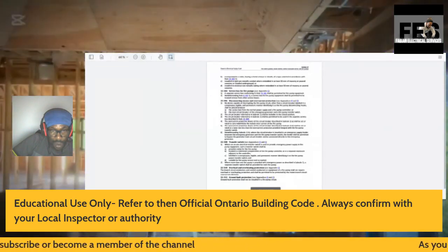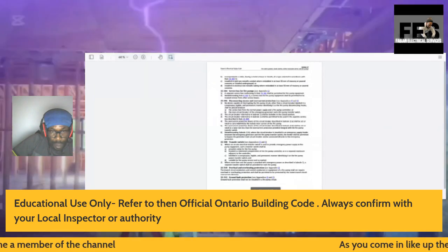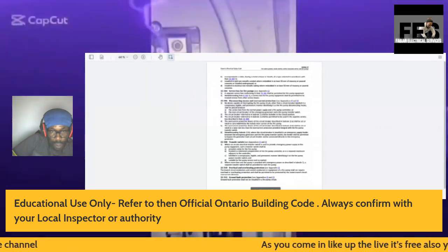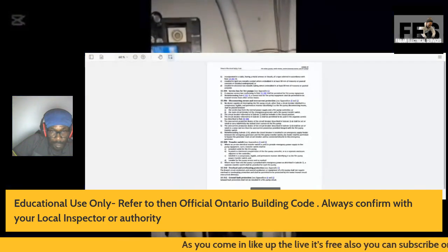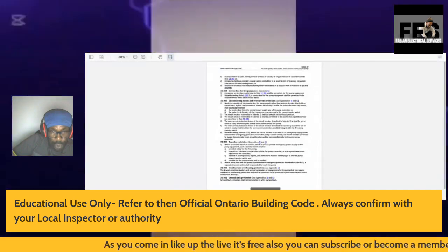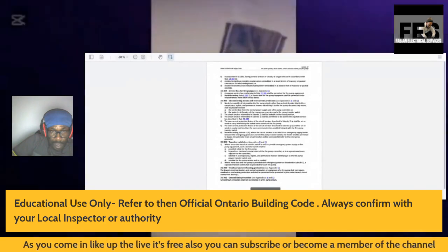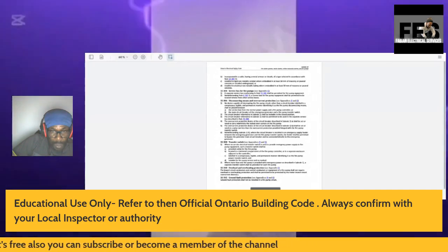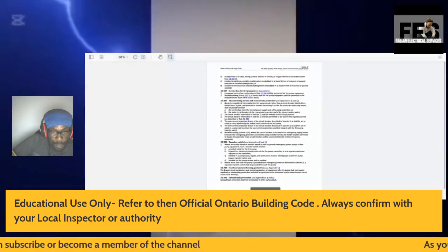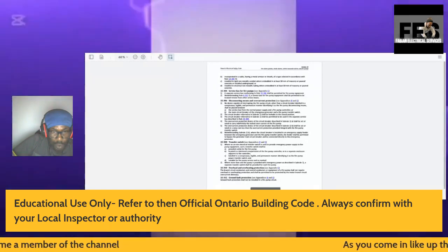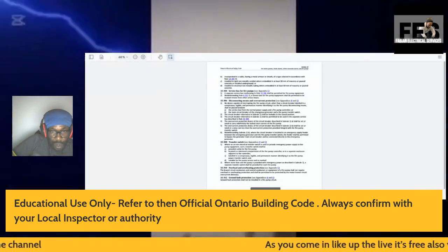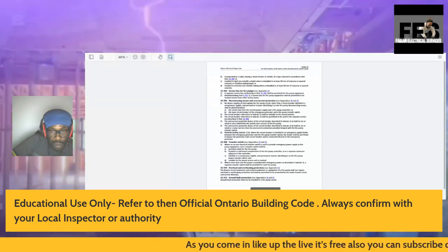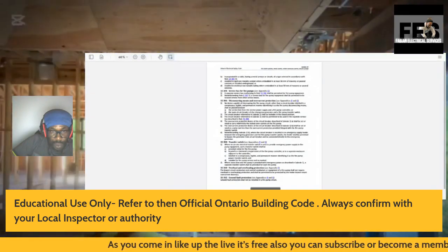The overcurrent protective device of the circuit breaker described in Subrule 1A shall be set or rated to carry indefinitely the locked rotor current of the fire pumps. The overcurrent protective device of the circuit breaker described in Subrule 1B shall be set or rated at a value not less than the overcurrent protection provided integral with the fire pump transfer switch.